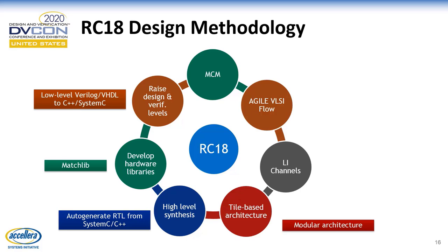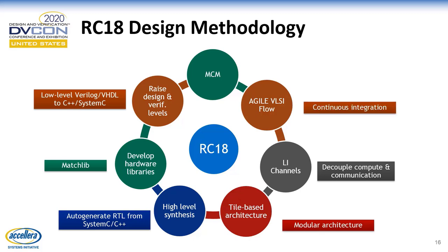And our choice of tile-based architecture ensured that there is modularity at the architecture level. We decoupled the compute and communication using our LI channels. Our LI channels also enabled a clear abstraction between the IP blocks and the high-level synthesis blocks, which communicate through a standard latency-insensitive channel protocol. We had an agile VLSI design methodology which enabled continuous integration and feedback throughout the design process and enabled daily C++ to layout runs. We achieved scalability by integrating multiple chips using multi-chip module technology.